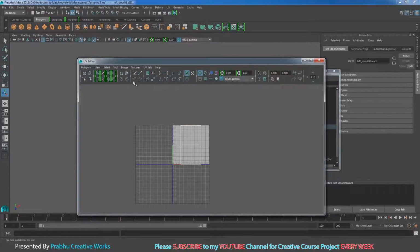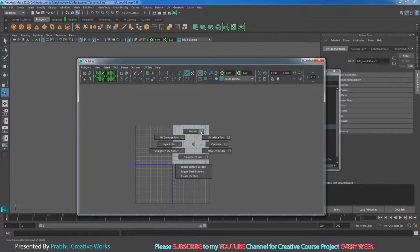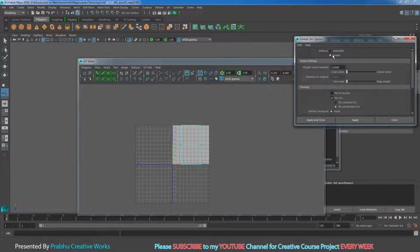So now I want to select this one. Separate the UV along the selected edge. So right click and choose UV. So now select the whole UV over here. Shift right click and choose unfold option box. Here you want to choose legacy and choose apply and close.